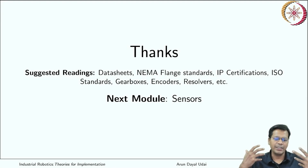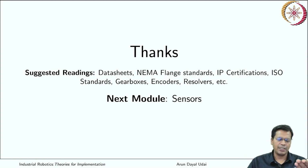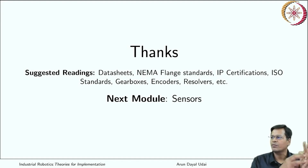The additional reading I have suggested here is data sheets. You should start looking for data sheets. If you see your robot, look at the motor model and try to get hold of that data sheet and see what the specification is, what gearbox is mounted, the NEMA flange standards, which one is fitted here, and the IP certification: is this enclosure safe for the kind of application I am looking for.